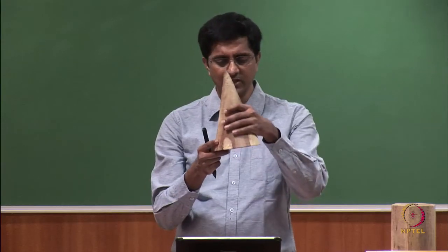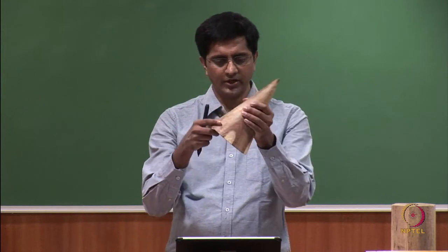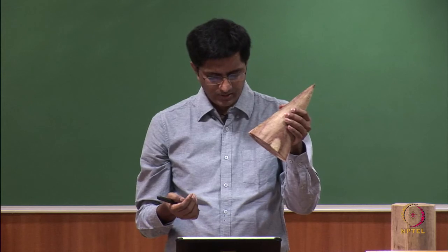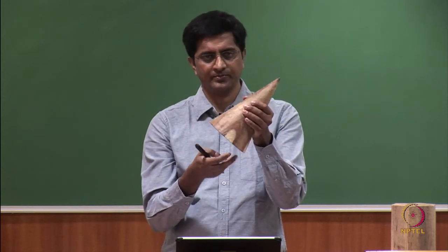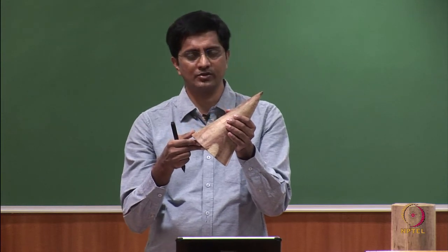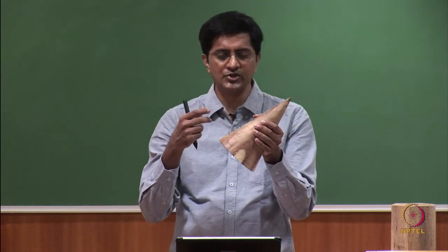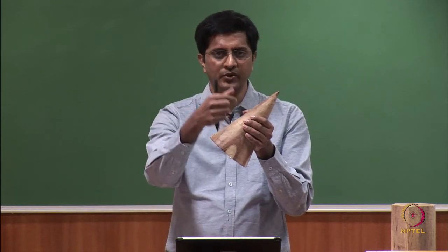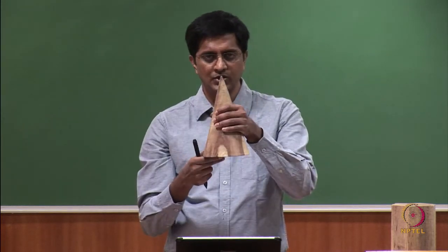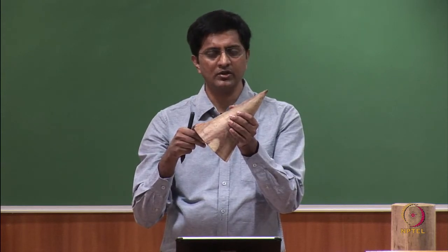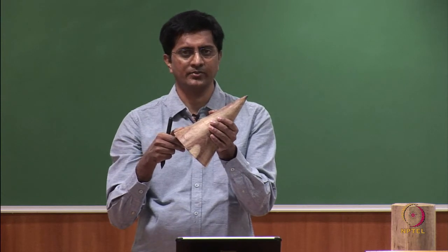So, the next thing we said is we will rotate it, so that the base makes an angle of 30 degrees with the horizontal plane. Okay, before rotation and after rotation. Again the same question. So, in which view is the shape being the same, the front view or the top view? So, in the front view you see a triangle. After rotation what do you see? You still see a triangle.